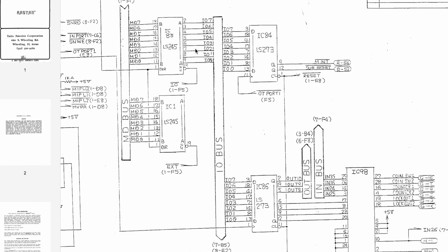And since that's coming from this 245 here, I could just go ahead and replace this chip, but I think I will connect the logic analyzer first and see if the inputs and the outputs match, which would mean that the problem is not this chip, that it's originating somewhere else.